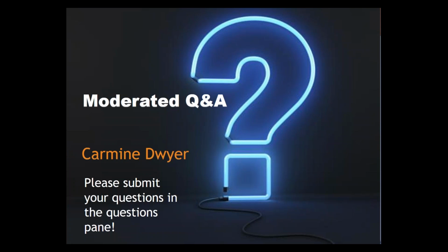Carmen, I just wanted to talk a little bit more about the hot spray thermo. We do include it on maintenance contracts, and we do have our own special provision for that material. From IDOT's perspective, it's really only intended to be a maintenance type of material where you're actually spraying it over some existing thermoplastic that has degraded or has faded. It's not really intended to be applied to a new surface or be a new pavement marking material. It's really only meant to be a maintenance material.